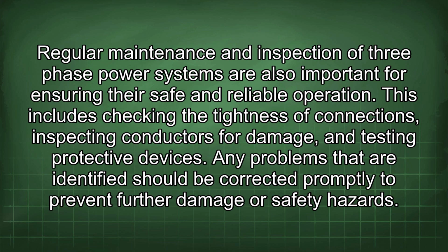Regular maintenance and inspection of three-phase power systems are also important for ensuring their safe and reliable operation. This includes checking the tightness of connections, inspecting conductors for damage, and testing protective devices. Any problems that are identified should be corrected promptly to prevent further damage or safety hazards.